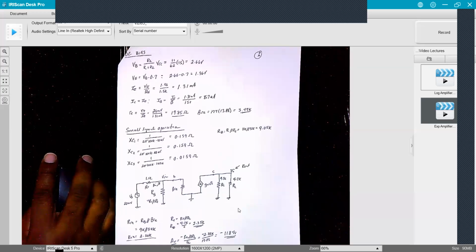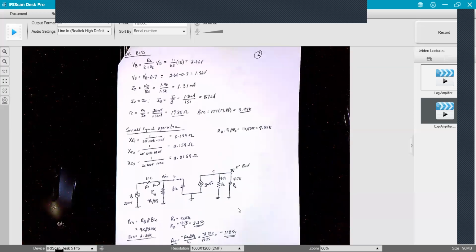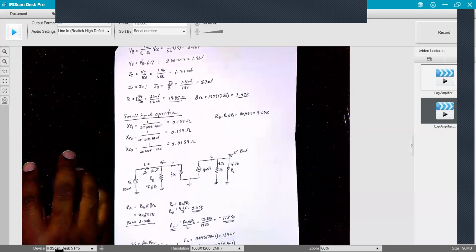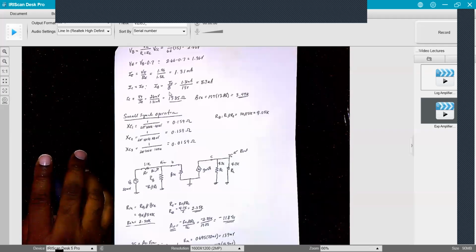I have two quick questions. It's about IC. Is that I beta, or IB equal IE over beta? This is IB equals IE over beta. Okay. And also, is that milliamperes for that 8.7? No, microamperes. Yeah, 1.31 milliamp over 150 gives you 8.7 microamps. Okay, thank you.